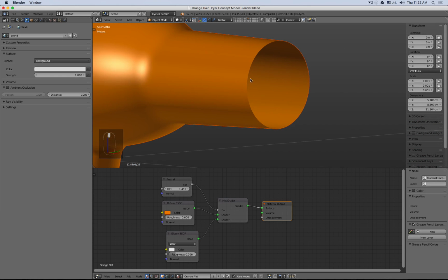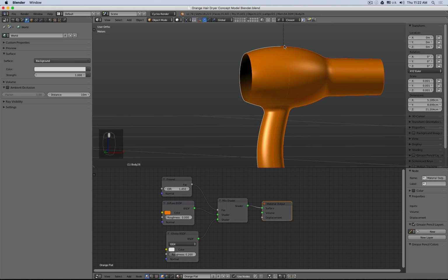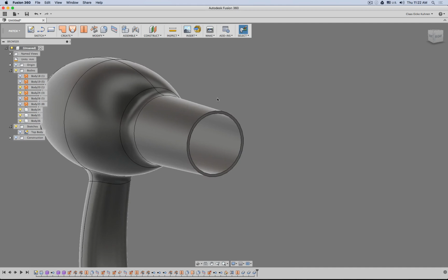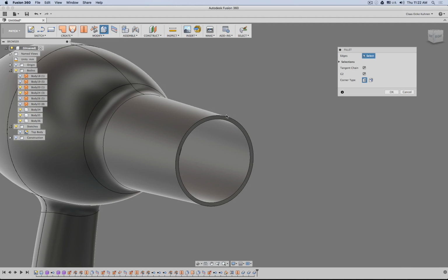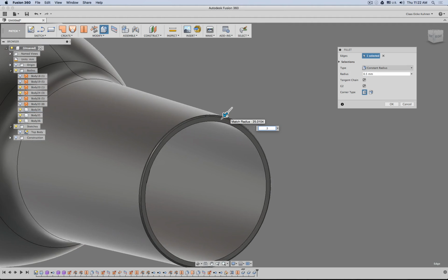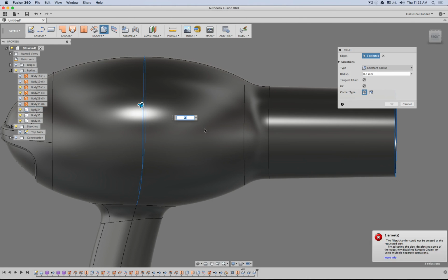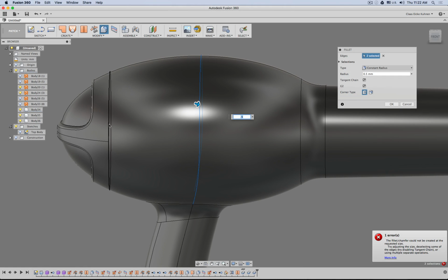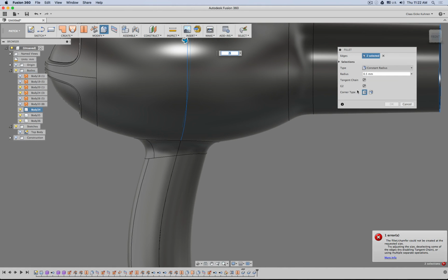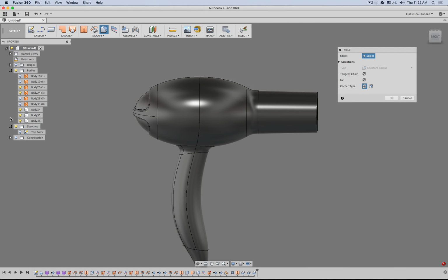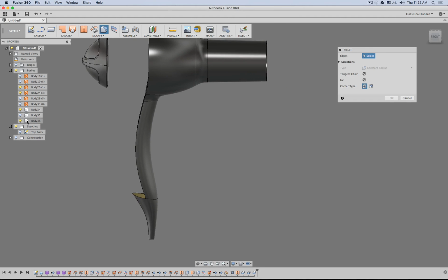That is a paper shell. And I don't have any material separation line, and it won't be so perfect. So adding a little bit of material first gives you the ability to show thickness, and now also here, hold on, we might actually have to do this object by object. So hide this one. Yeah, perfect.